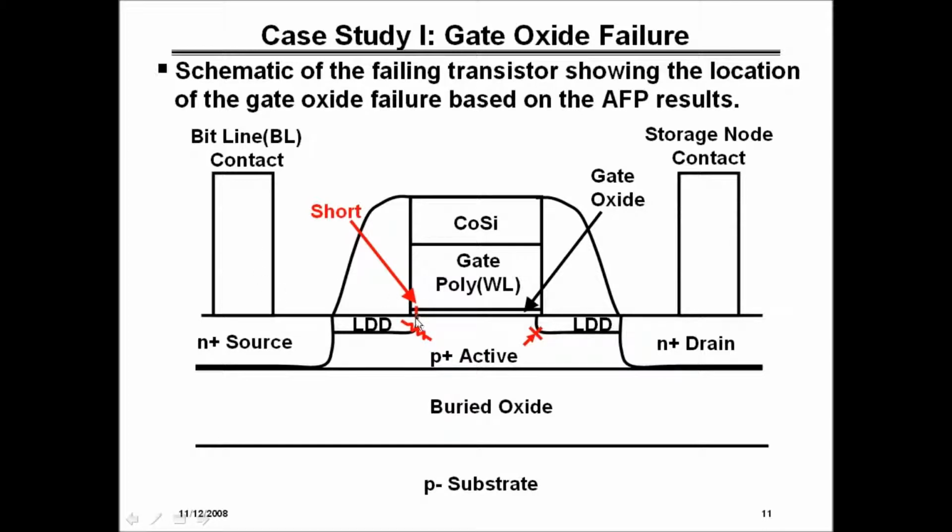and the bit with the gate oxide leakage was the signature bit. And then we saw on the previous page, when we swept gate to drain, you saw the diode. That was this junction here. And then sweeping source to drain also. Again, because this junction no longer exists, when you sweep it, you see this diode also.